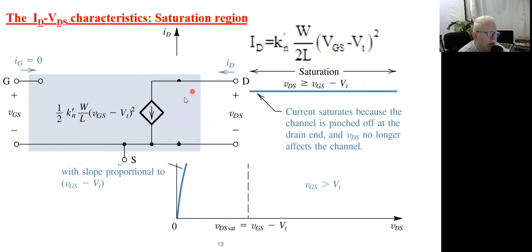This is what we call, my dear students, a voltage dependent current source, because the value of the current here is dependent on VGS, which is an input in our system, in our transistor. I believe you already saw this circuit schematic before in your circuits module. So this is a voltage dependent current source that depends on the voltage coming from the gate. So whenever the voltage on the gate increases, the current flowing in this current source increases. This is the case. Okay, perfect.